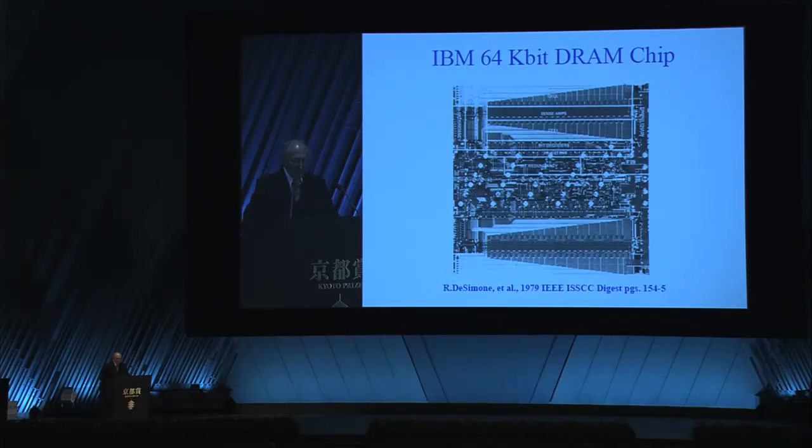At first, it seemed to have a simple solution. Why not modify the package or introduce a barrier layer, such as a plastic film, between the chip and the package? When experiments like these were done in various labs, the error rates dropped substantially, but did not go away completely, presumably due to radioactive impurities in the on-chip materials. Also, an analysis of the possible soft error rates due to cosmic rays showed that this source could be significant.